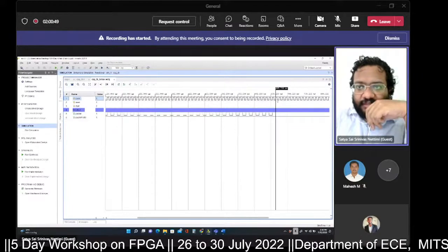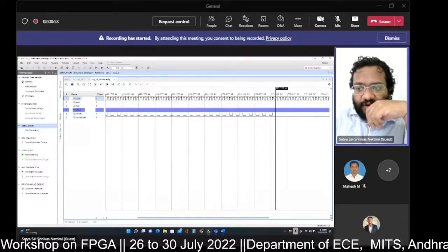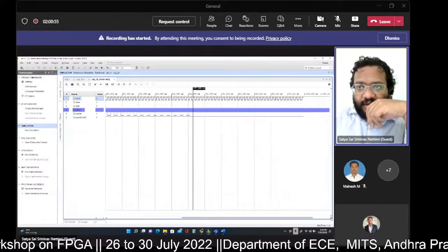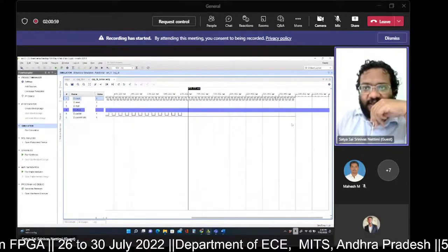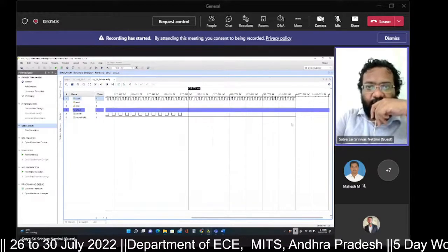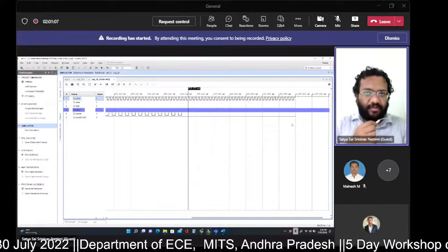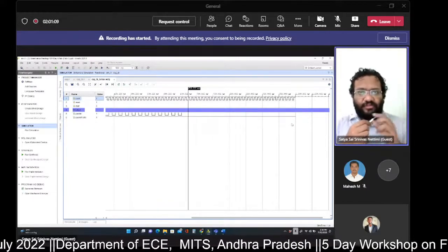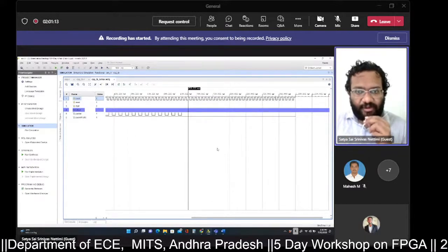In the next clock cycle also it is 1, but it is not 0, it's not alternated. And after this clock cycle the data is still high, so that is invalid. So up till the marker whatever I have kept, from here to the start of the frame, I think 64 bits are definitely available.